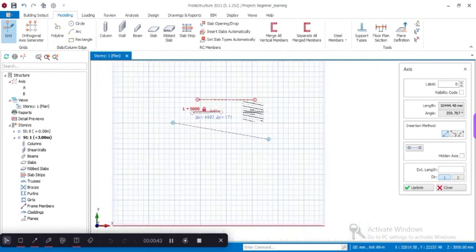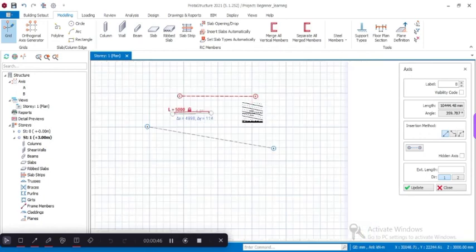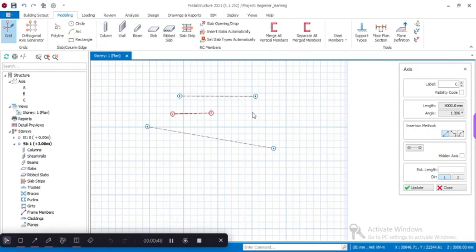So now immediately I press Enter, it will automatically pick the line for me. The points will be picked. So that's what it means there. Then in either of the text boxes, you can use shortcut notations, length, stroke angle, or delta x, delta y, without the need to switch by Tab.